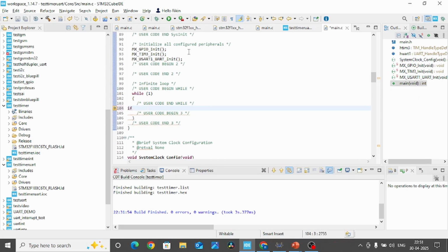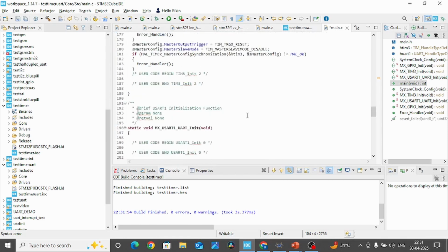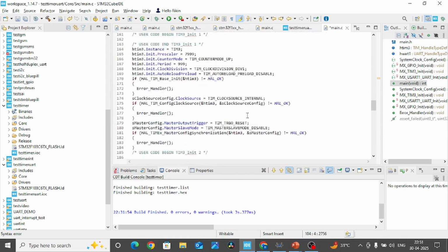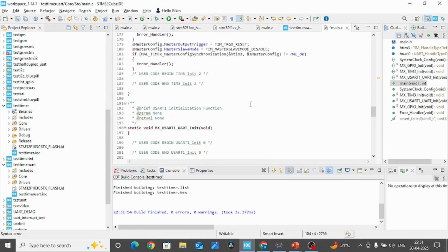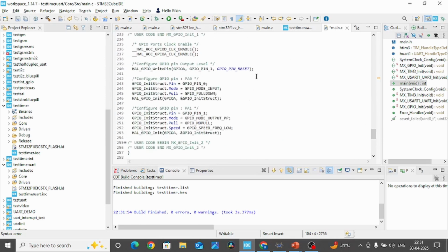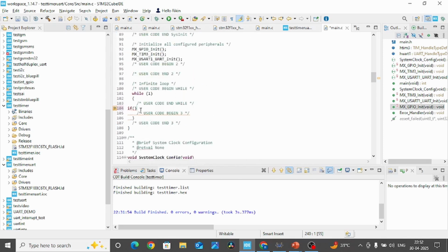our first task is to detect if our pin 0, so let us reuse this. Okay, in HAL we have the advantage that some functions are pre-implemented, right? So let us reuse them. No need to remember everything, just reuse them. Now using this write pin function, you can also convert this into read pin. How? Simply here change this write to read.